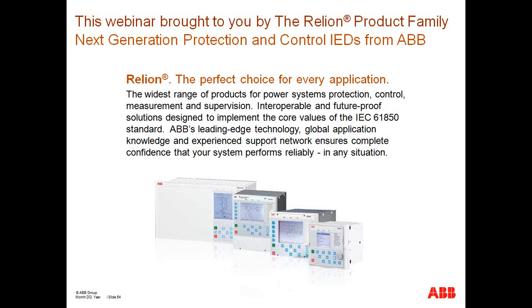That's a very good question. From a NERC CIP perspective, you're really addressing routable protocols, and GOOSE messages are not a routable protocol. From the regulations perspective, you're looking at protocols that have the capability of going over different networks that are impacted by the NERC CIP regulations. Also, NERC CIP regulations become a concern from a station bus perspective if there's a connection to the outside world from that substation.